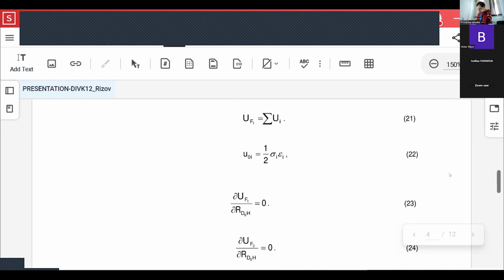Then the strain energy release rate is derived by using equation number 10. A checkup of the solution is done by applying equation number 18. The strain energy release rate in the frame in figure 1b for the load F2 is determined too. Equation 24 is applied for dealing with static indeterminacy. After that, the strain energy release rate is derived by using equation number 10. The result is checked up by using equation number 19.